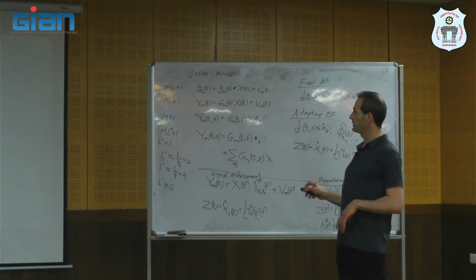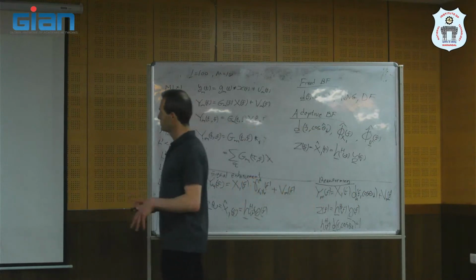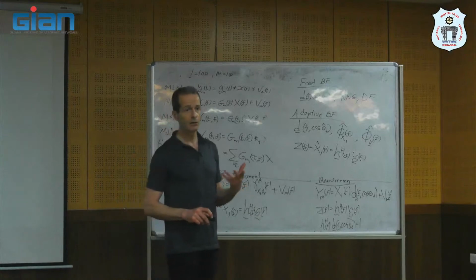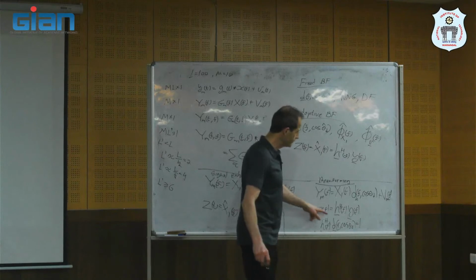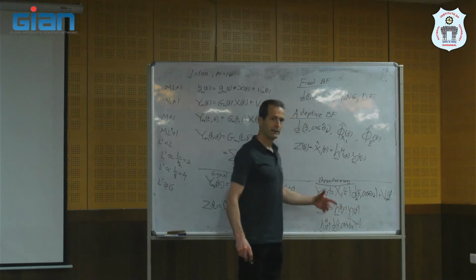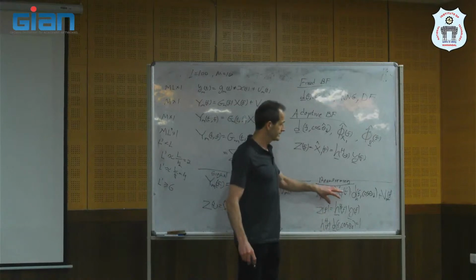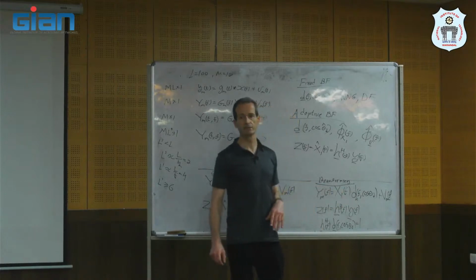And then we talk about signal-to-noise ratio. We have input SNR, output SNR, and the gain in SNR. The gain in SNR means how much the SNR at the output of the beamformer is relative to the input SNR, which is the signal-to-noise ratio at the reference sensor.